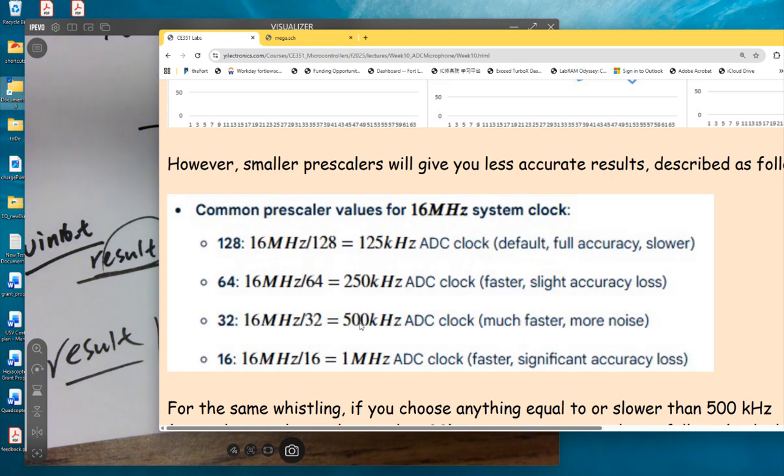Because this has to be ready first, so that when the 13 cycles are done, the conversion is done and the data is available. Then you sample, right? It's 13 clock cycles per sample. Yeah, that's the ideal case, but usually you want to slow it down a little bit, and you don't want to directly use that.